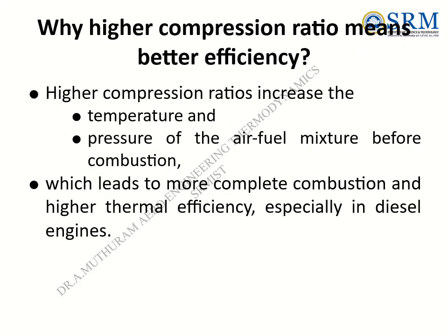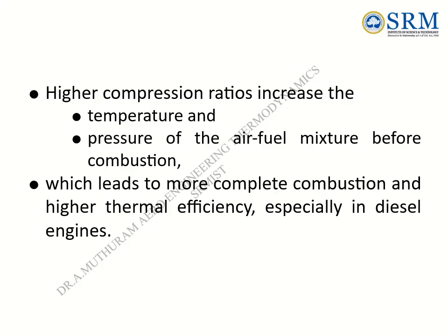Higher compression ratio means better efficiency: higher temperature and pressure of the air-fuel mixture before combustion, which leads to more complete combustion and higher thermal efficiency, especially in diesel engines.